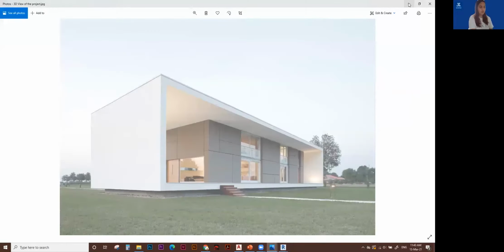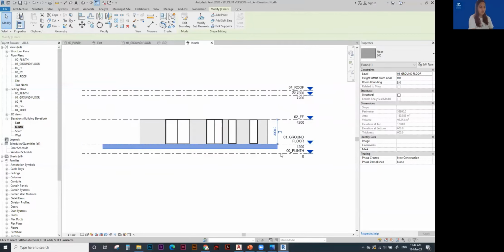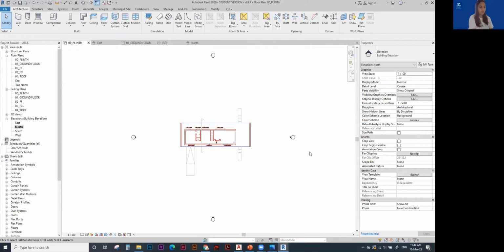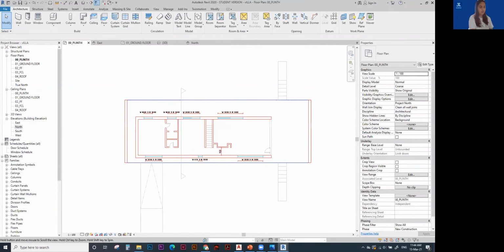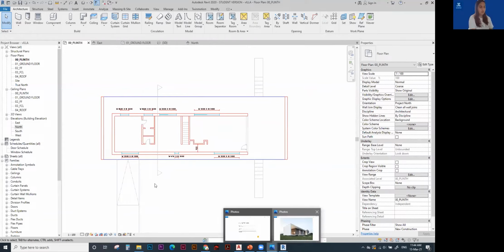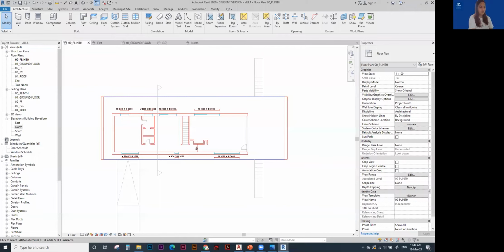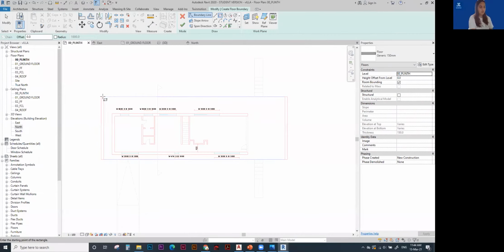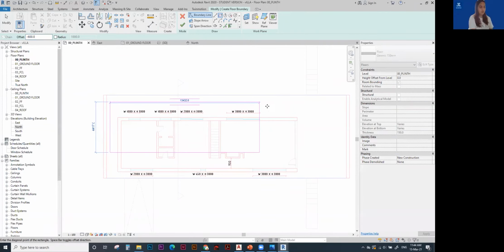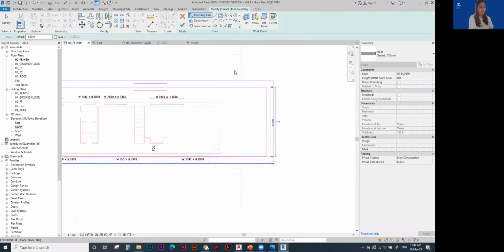Like I mentioned before, there's also a small detail of this pedestal that's happening below the ground level. So I'm going to go ahead and build that now. Let's see how to do that. For that, I'm going to go to my plinth level. Now, I can guess from the image that it's got a similar offset from the edge of the surface. So what I'm going to be doing is create a floor slab, but I'm going to offset inside it by 600. So I've given an offset of minus 600, and then I'm going to draw this line.